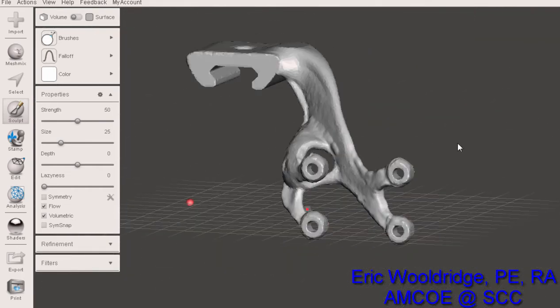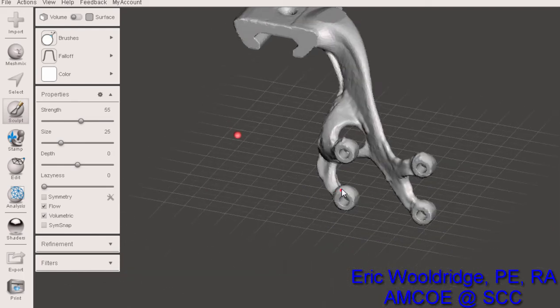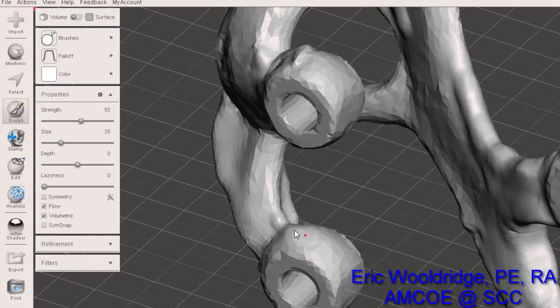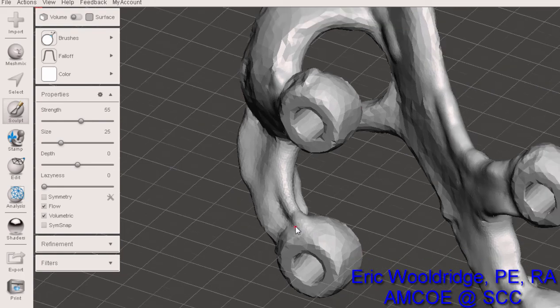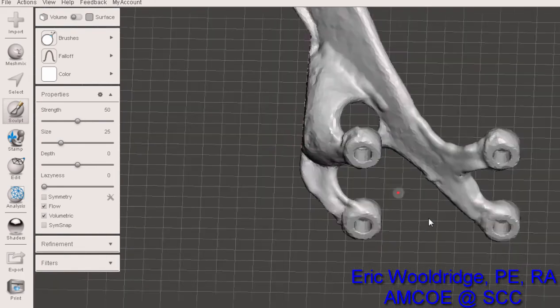Alright, thanks for watching, and make sure you practice this if you're in this generative work, because this can really give you an advantage in the part creation that you make, and even a really unique feature to them as well. And you get a feel for it over time. Whenever in doubt, you can always look at bones and do Google searches for organic structures and bones, and you can get a feel for how ridges and little areas like that can create extra stiffness that you need.